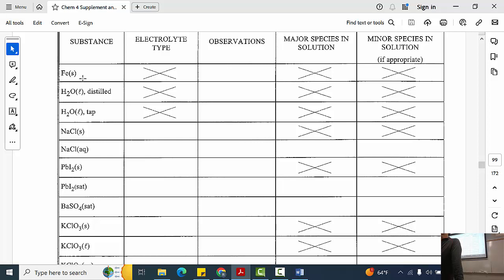Well, air is not a good conductor of electricity because there's an air gap here, and the electrons aren't flowing through the air gap. I can get the electrons to flow through the air gap. Do you know how electrons can flow through the air? You've seen it before. Everybody's seen lightning, right? Those are electrons flowing through air, but what do you need in order to create lightning? Well, it depends on how big the gap is. For a gap this size, you'd probably need a couple of thousand volts.